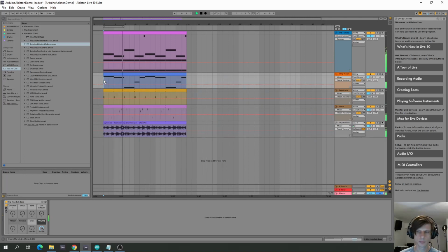So, as you can see, now it plays without a problem. But if you hear this in your track, you should straight away think, okay, this is the synchronization. This is really the Max for Live trying to send too many serial commands to that Arduino. And you know now where to go to fix it.